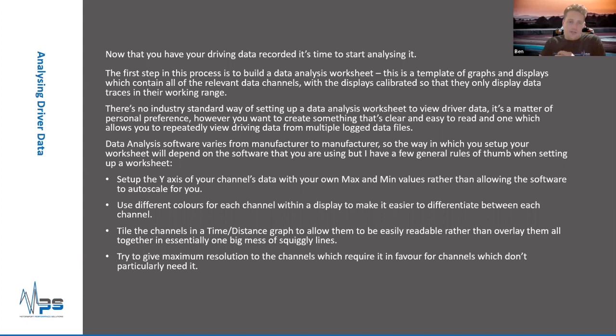The first step when you analyze your data is you need a thought out, well-defined, what I call a worksheet, other people call a workbook. This is a collection of graphs and data displays which are thought out and are for the purposes of what you're trying to achieve. So I do this professionally. I don't just look at driver, I look at engine reliability, gear shift quality, suspension data, car performance channels.